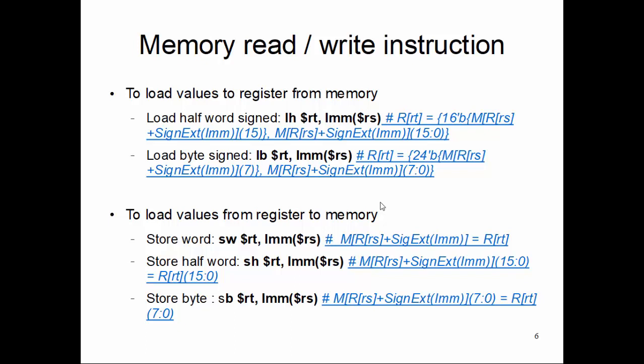You are just doing all the 32 bits loading, reading from the memory from a starting address, consecutive 4 bytes are read and returned to the processor. The whole 32-bit is kept in the register. There is nothing like a sign. If that value is treated as signed, you treat it as signed. If that value is treated as unsigned, you treat it as unsigned. So that 32-bit has nothing to do with the sign notion. So there is no signed word and unsigned word loading.